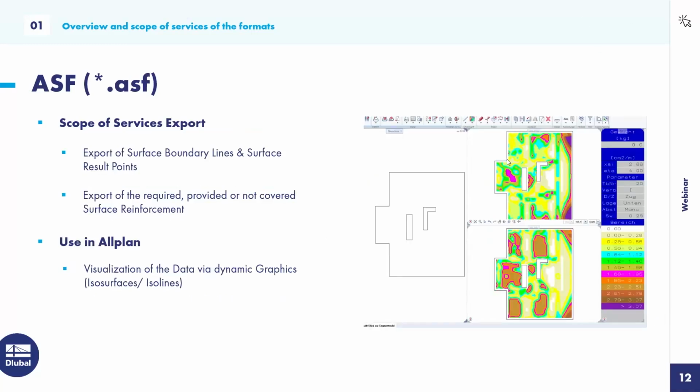Okay, the next format is the ASF format. So we kind of remain in the Nemetschek world and Allplan world. It was, or it is, a format especially for the data exchange of reinforcements, mainly for Allplan, but I think also other concrete detailing programs support the ASF import.